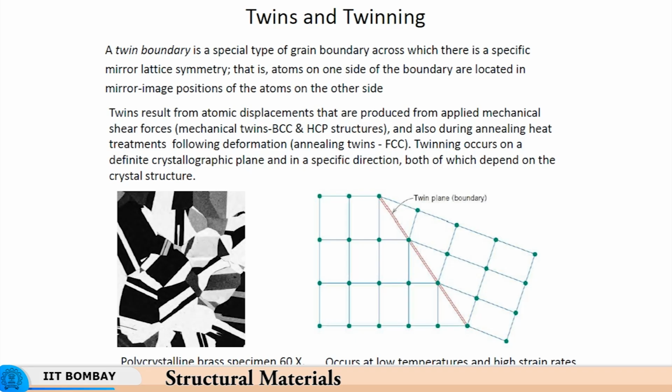and it shows itself in this form in a microstructure. If you look at a polycrystalline material like brass, for example, twinning takes place. While rolling, you will see that the material develops these twins. Similarly, austenitic stainless steel also develops twins. These are called mechanical twins, because they have been formed as a result of applied mechanical working. But there are other reasons twins can form.